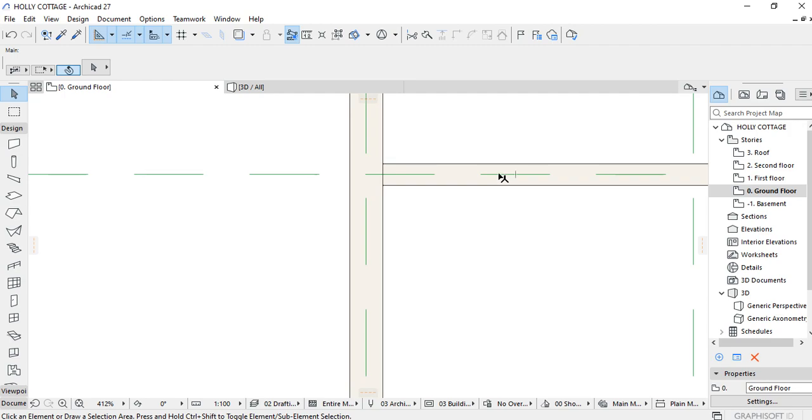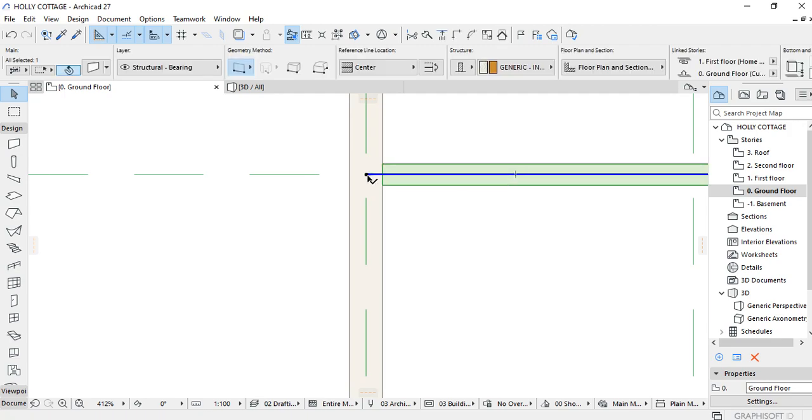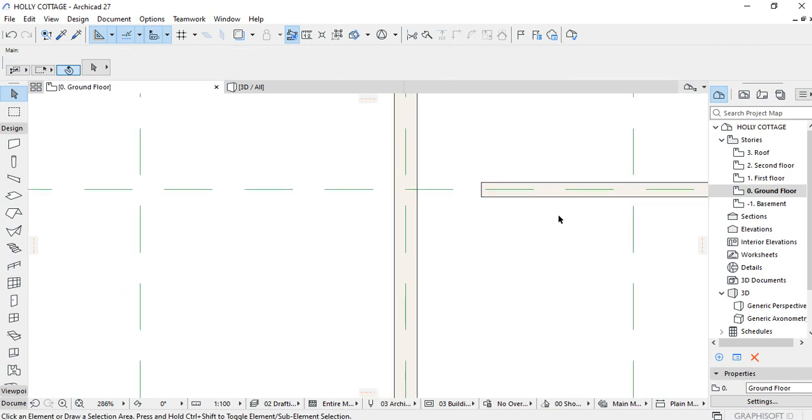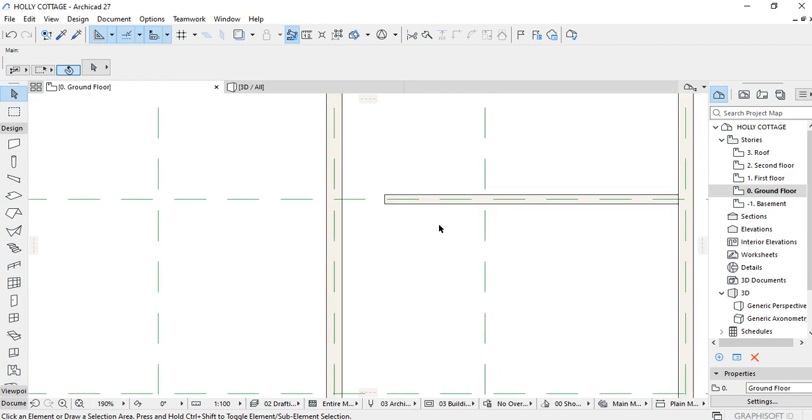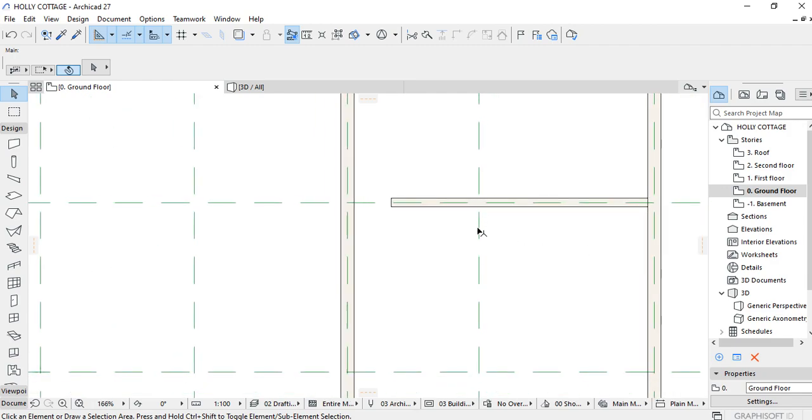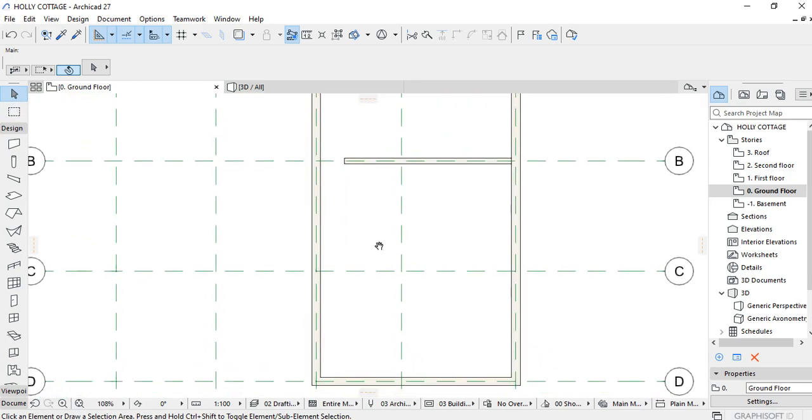So again, you can select it. Then you could use the paint palette, stretch it through the shift key, and D, type in the distance you want to stretch it, say by 1,000 millimeters. So we've been able to reduce it by a distance of 1,000 millimeters. So if you want to draw a wall, say here to here, we could again draw our internal wall.